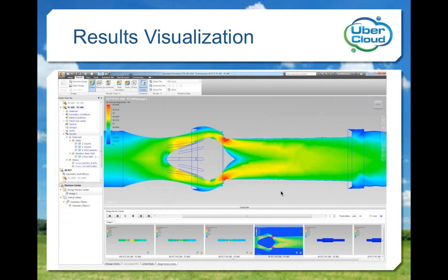There are many ways to view results in CFD, but this simple cross-section offers us a lot of information about the flow path. The abrupt changes in velocity magnitude that are observed will influence changes to the plug to smooth out the rise in velocity as the fluid approaches the restriction. Better management of velocity through the valve will reduce internal damage and vibration-induced noise.